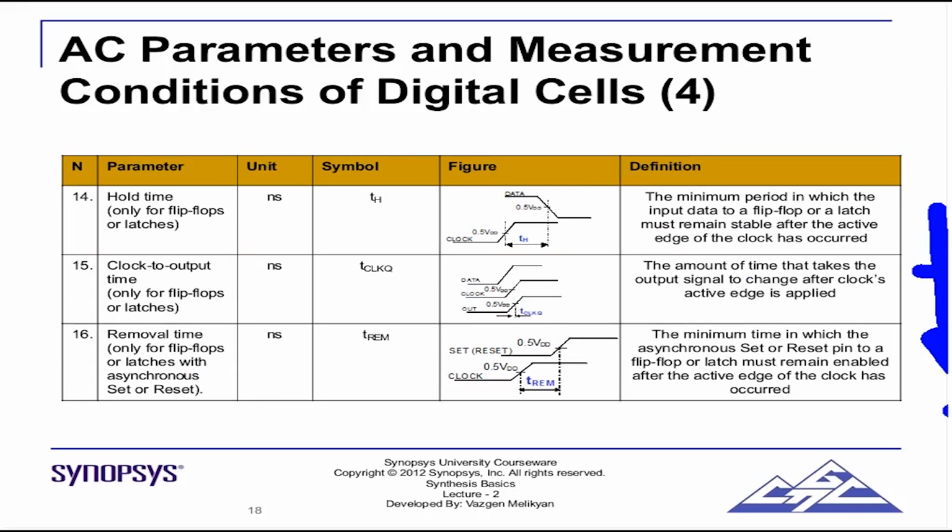Similarly, corresponding to hold, you have removal. Again, the deassertion is important. From a timing point of view, assertion is not. The minimum amount of time in which the asynchronous set or reset pin to a flip flop or a latch must remain enabled after the active edge of the clock has occurred. So after the active edge has occurred, the minimum amount of time during which this should remain deasserted is called T removal. It is just like hold. So setup is equivalent to recovery, removal is equivalent to hold.